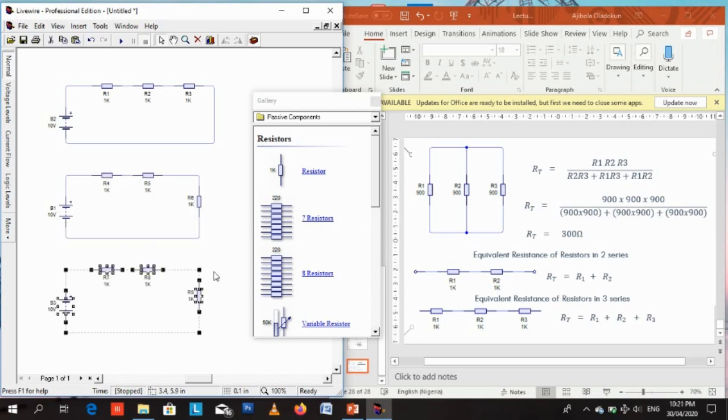Copy and paste. There's a third way you can do it, and that way you can connect all three resistors in series and still be the same thing. Let me delete this wire, rotate once again to the right, drag it down here, delete this wire, click, rotate to the right, and drag it down, and then click and drag, click, connect, click, drag, click, connect. So basically all three circuits are the same thing.